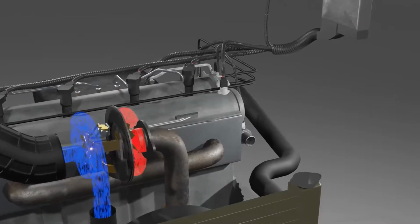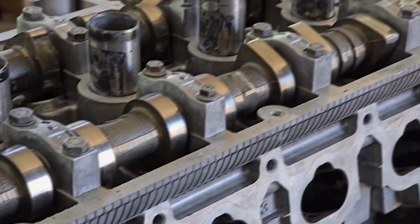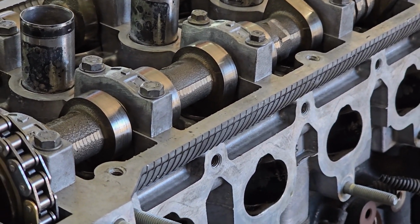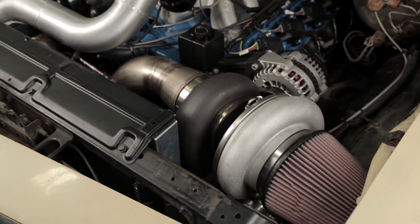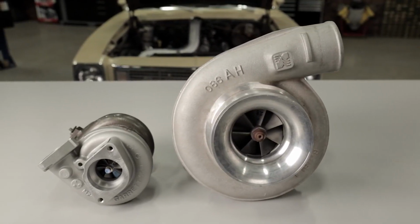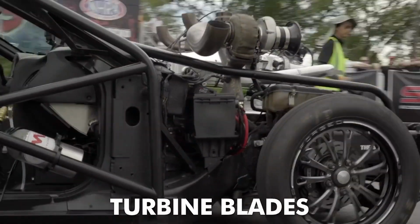A turbocharger's core components are the turbine and compressor, which are both mounted on a solid shaft. The turbine section consists of a turbine wheel housed within a specially shaped turbine housing that directs exhaust gases from the engine to the blades of the turbine wheel. This housing is precisely engineered with a volute spiral shape that increases the velocity of exhaust gases and guides them efficiently onto the turbine blades.